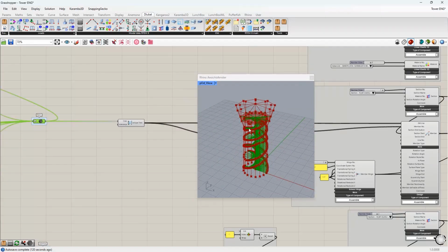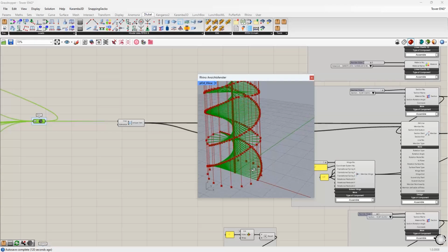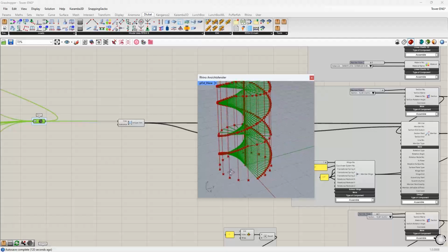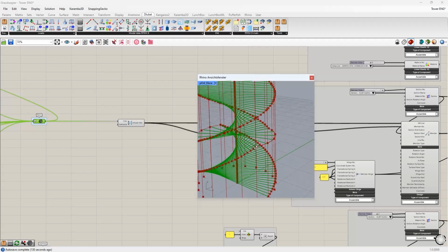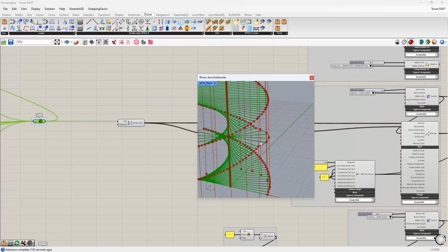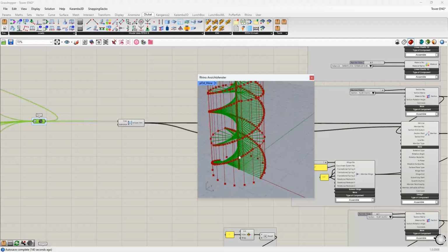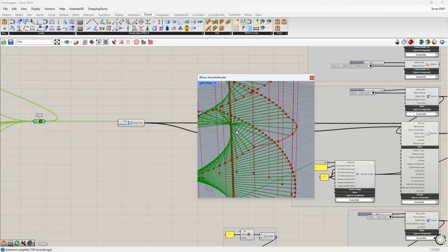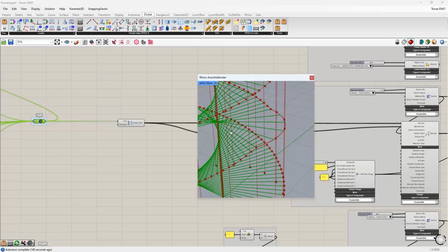Maybe I show it like here. Yeah, lines from our stairs. And here I have maybe also a hint from my side. I had some problems with double lines, because as I generated the stairs, the last stair of the line is also the first line of the platform here. So I always get double lines at these areas.